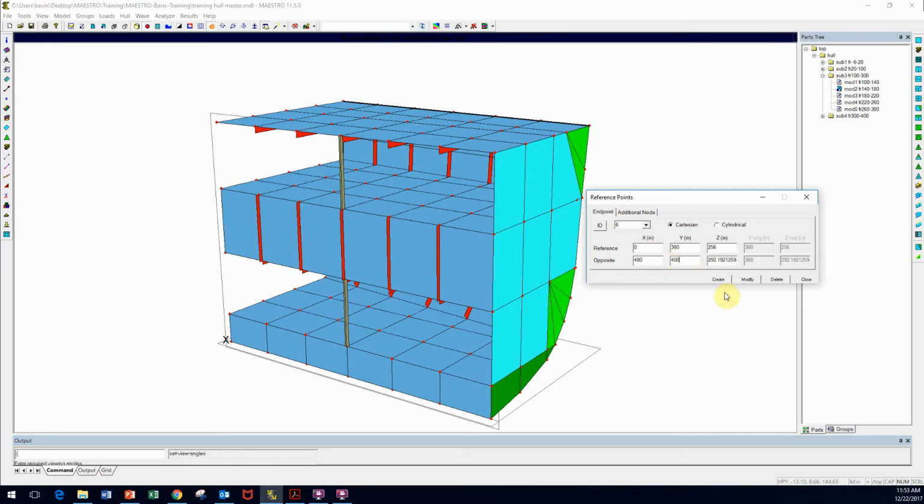Just enter 400, I modify it. The structure has now moved with it. And by this you can see how the strake, this blue structure, has all moved with it. It's easy to move back. I move it back to its correct point, enter 360, modify it, and it's back.